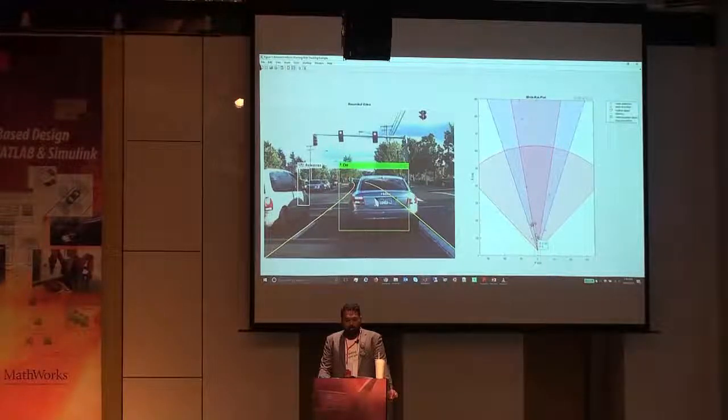Right, right. So this involves multiple stages. I purposely didn't go into the full details of the workflow for this example. First, the radar detections need to be filtered because they're so noisy. We actually use a Kalman filter simply for the purpose of removing spurious radar detections.